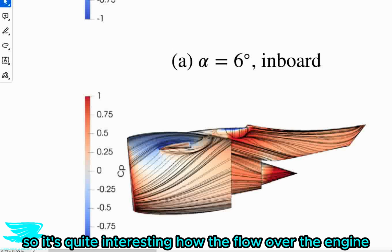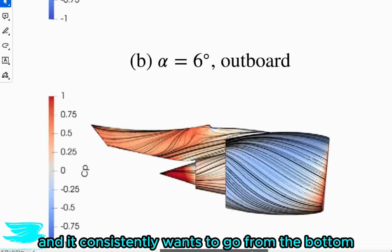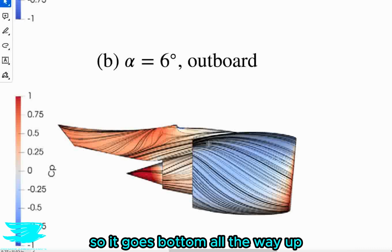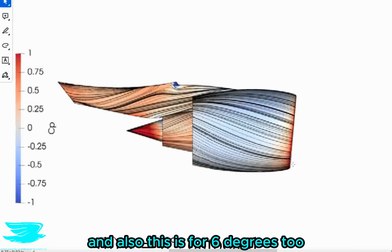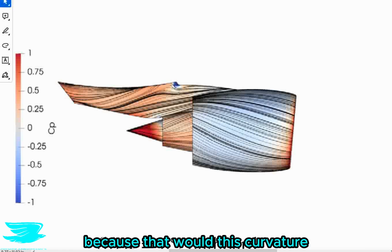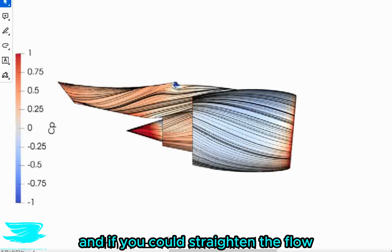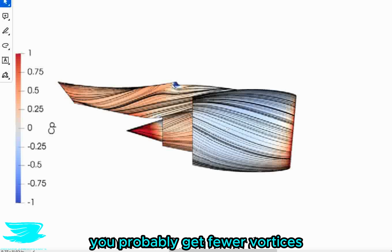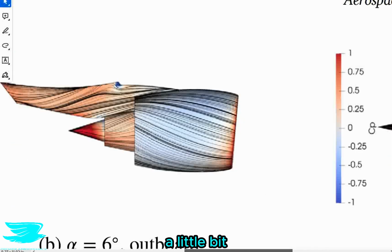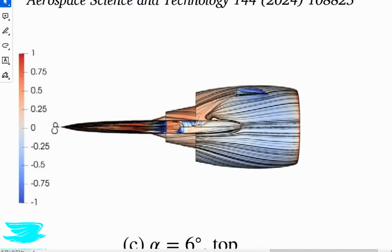So it's quite interesting how the flow over the engine on the outside moves up, and it consistently wants to go from the bottom to the top of the engine. So it goes bottom all the way up. And also this is for 6 degrees too. So I wonder how you'd be able to straighten it up, because this curvature would increase the vortices being formed on this engine. And if you could straighten the flow, you'd probably get fewer vortices and also reduce the effects on the engine. Maybe that's what this fin is supposed to do a little bit, perhaps straighten the flow in some sense.